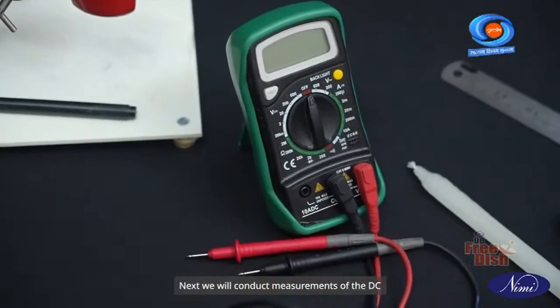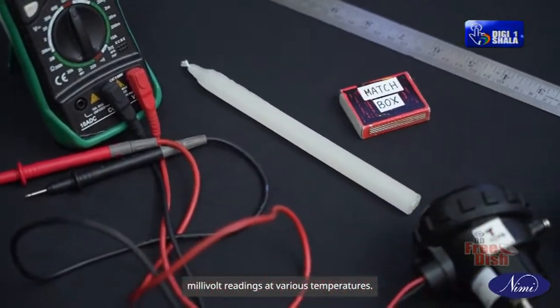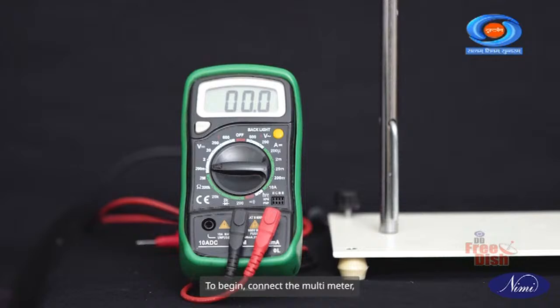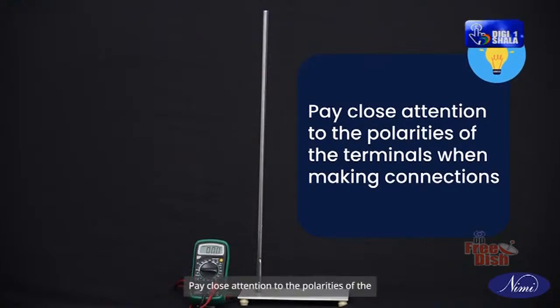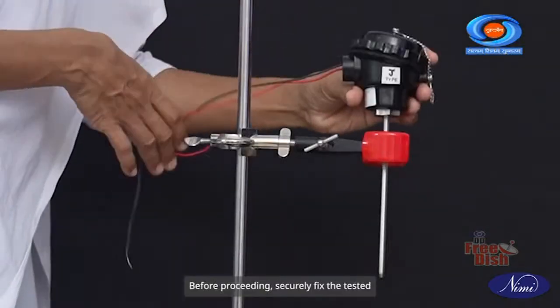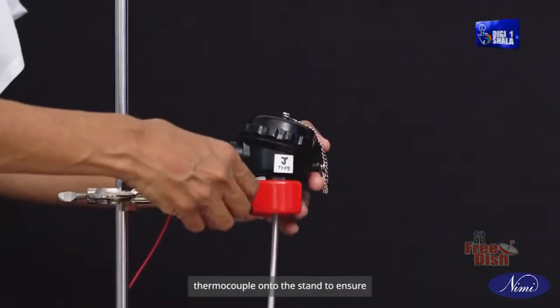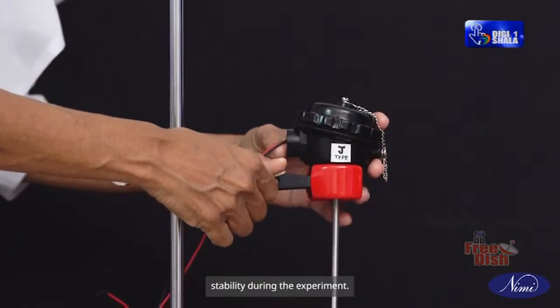Next, we will conduct measurements of the DC millivolt readings at various temperatures. To begin, connect the multimeter initially set to the low DC millivolts range. Here is a safety tip. Pay close attention to the polarities of the terminals when making connections. Before proceeding, securely fix the tested thermocouple onto the stand to ensure stability during the experiment.